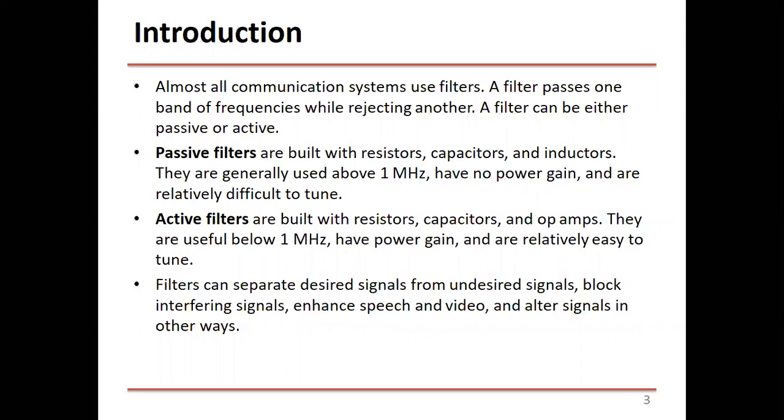Why is that? Okay, we'll go back to the frequency response that we covered a long time ago, because these devices have a limited frequency response, right? And most of them work fine up to 1 megahertz. Above that, you have the output stray capacitors or internal capacitors that will limit this frequency range.